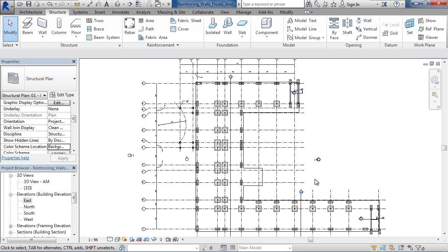So as a review, in this lesson, we looked at creating rebar or other reinforcements in walls, floors, or slabs. We added the rebar from a profile or a section view or elevation view of the floor for which we wanted to add the rebar within. We started the rebar tool, verified its placement, selected the actual profile or shape, and then placed it inside a structural member, such as the floor. Then we visually looked at the floor plan and then turned on the shape by editing the actual state of the rebar within the view.